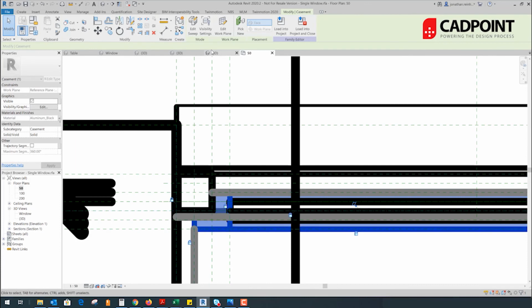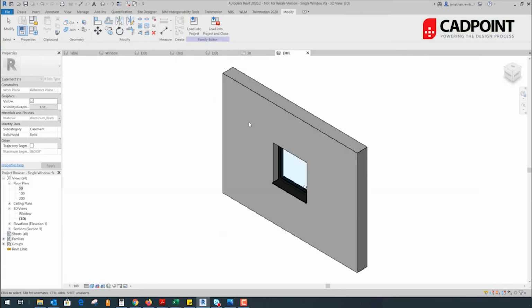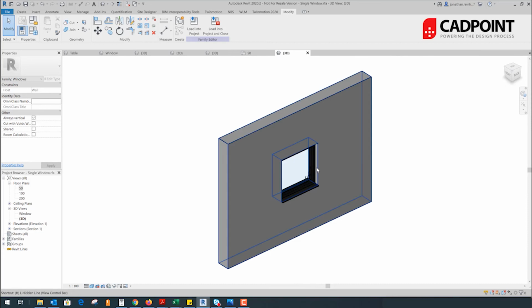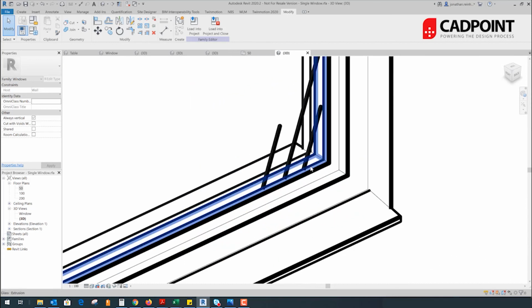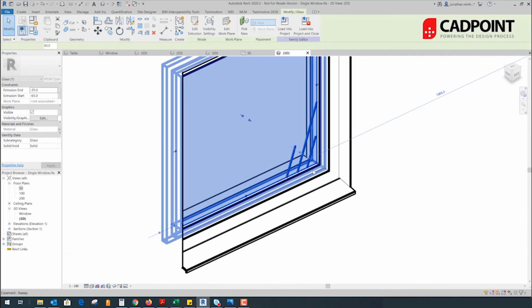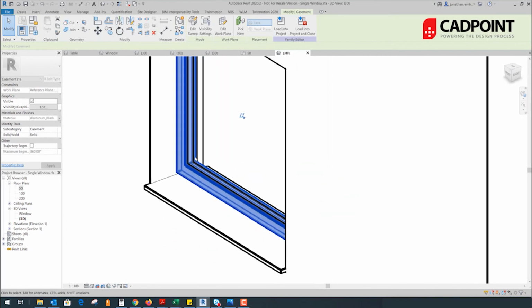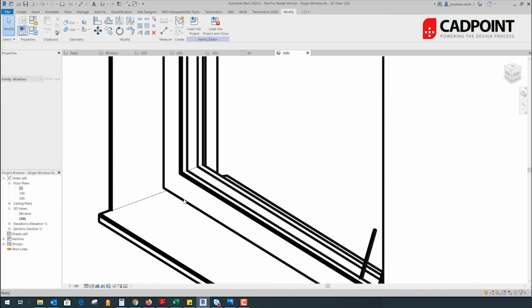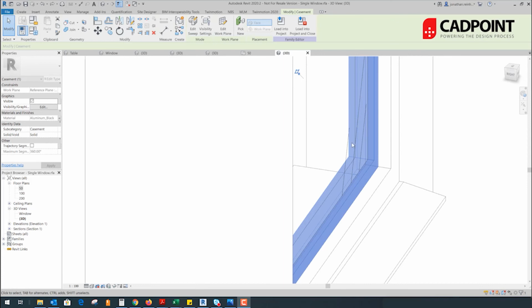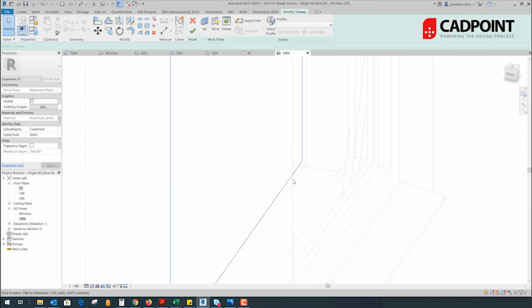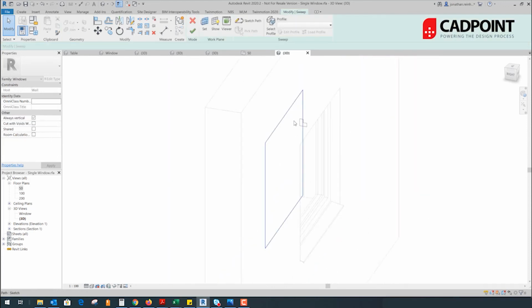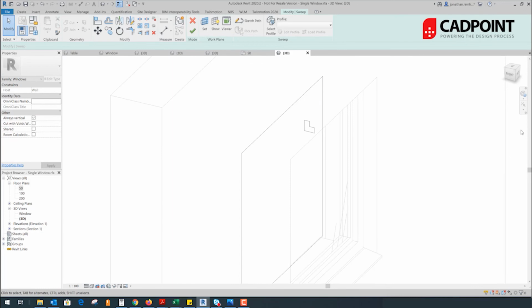The way that was created was using something called a sweep in the geometry creation stage. So if I select, that's the glass, for example, that's my window frame, just to make sure I'm selecting the right object. So what I can do is select that piece of geometry. It's a piece of the window, the casement. I can edit that as something called a sweep. What a sweep allows you to do is to trace an actual path of geometry.